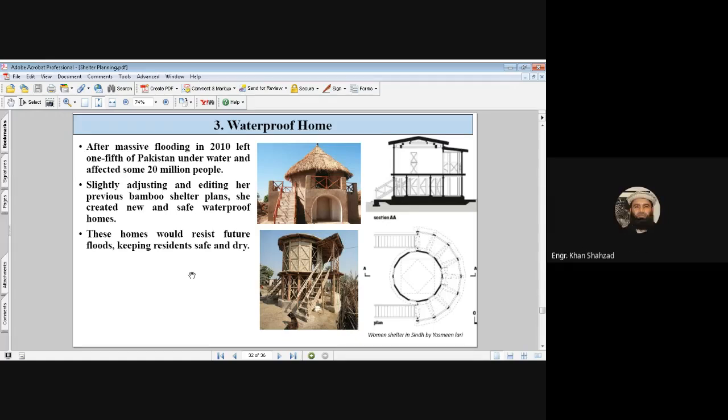Yes, we have used even these hairs or these ears in concrete. One of my MSc students, Fawad, has done his research on this topic and he has done a very good job. Its strength increases as compared to the normal strength concrete, especially the tensile strength. And with the help of this, it can prevent the spoiling of the plaster if you are using this in the plaster mortar.